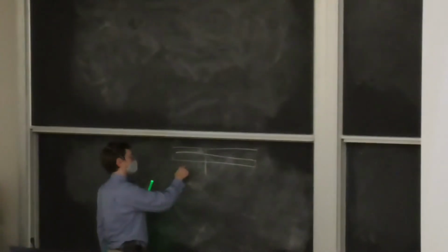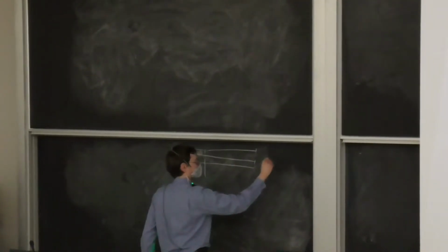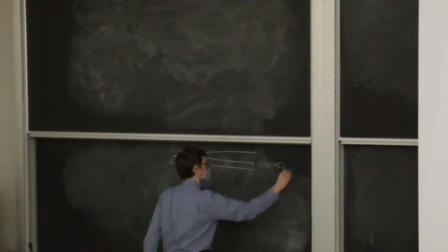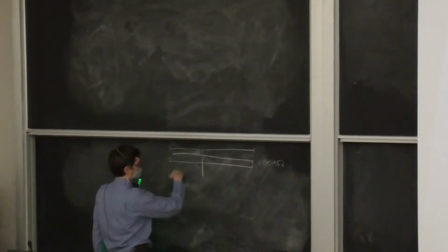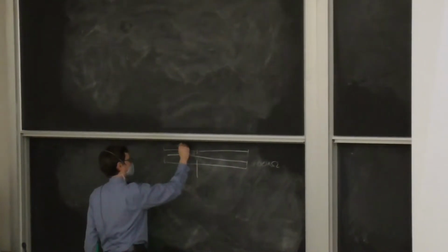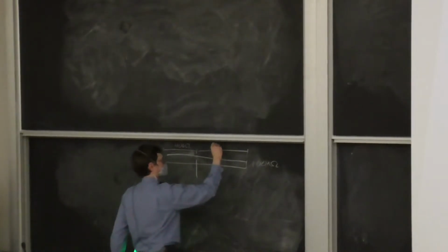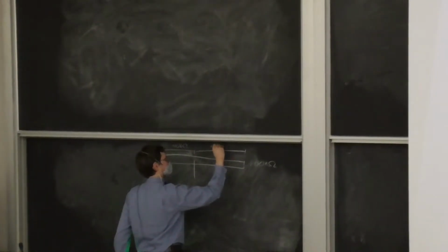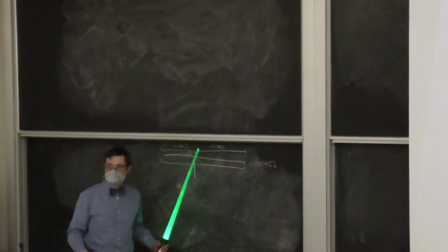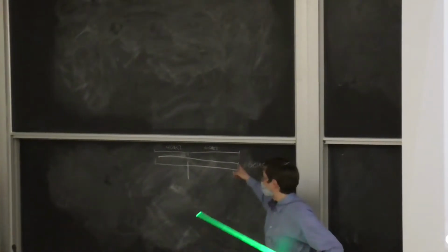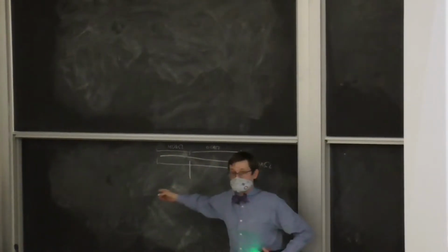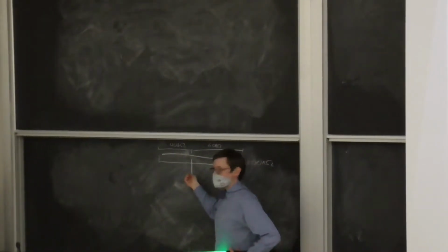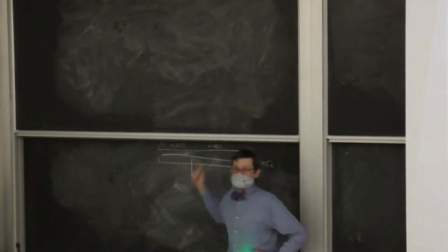So if this whole thing is 100 kiloohms, and it's 40%, you'd have 40 kiloohms on one side and 60 on the other, right? Make sense? Yeah, good. And you can see how, if you applied high voltage to one side, low voltage to the other, you would get a voltage here according to that ratio, right?